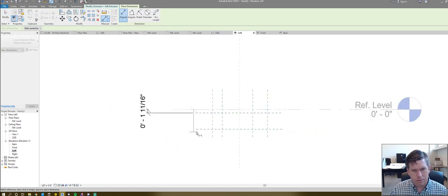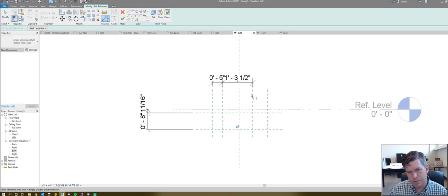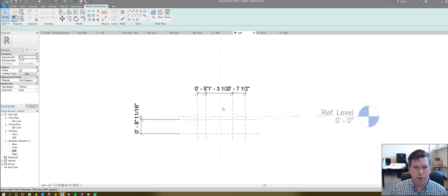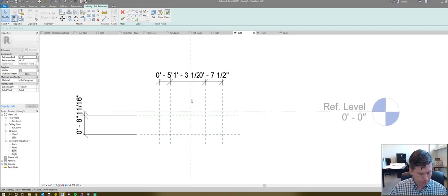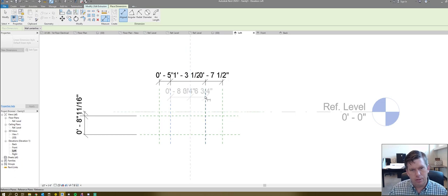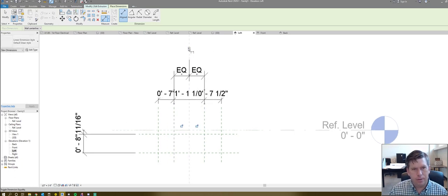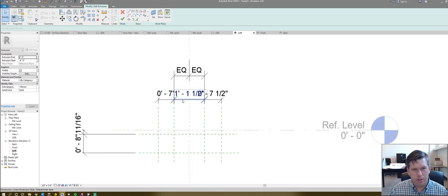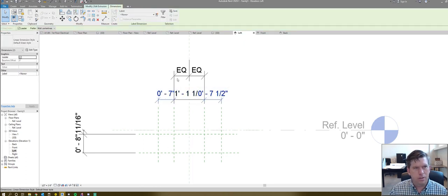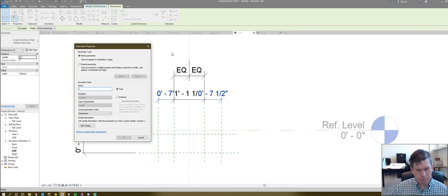We're going to draw some dimensions here. And these need to be individual so that you can assign parameters to them. And we want to EQ this so that it's equal around the center. Keep that EQ'd. These guys, let's go ahead and make that turn down width.